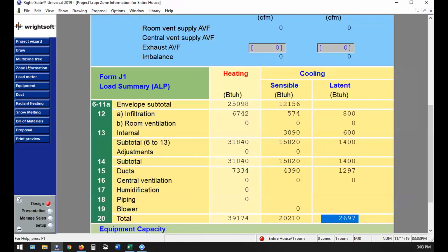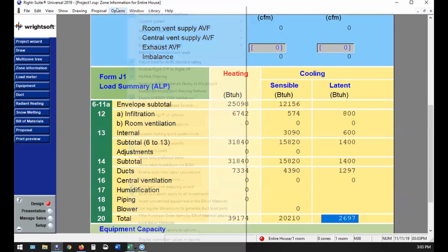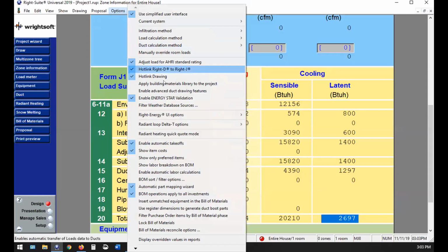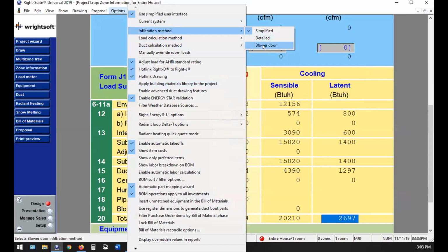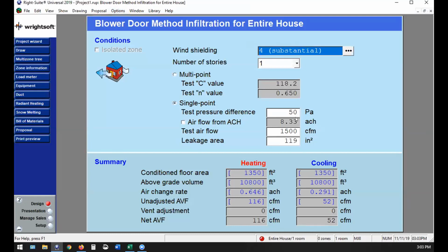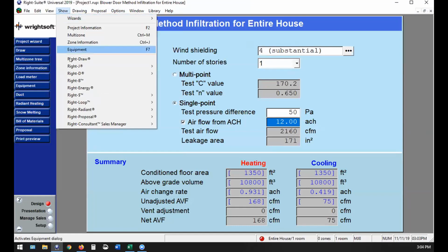So while you're working on the next one, or this example here, the next question would be, do you know if it's a standard rule of thumb that an AC condenser cannot be larger than the coil? No. That is a very common thing for home inspectors to say. I don't know why, but it comes up a lot with home inspections. And that's not true at all. You can match up coils and condensers any way the manufacturer matches them up. They have one of those sheets for all of them.